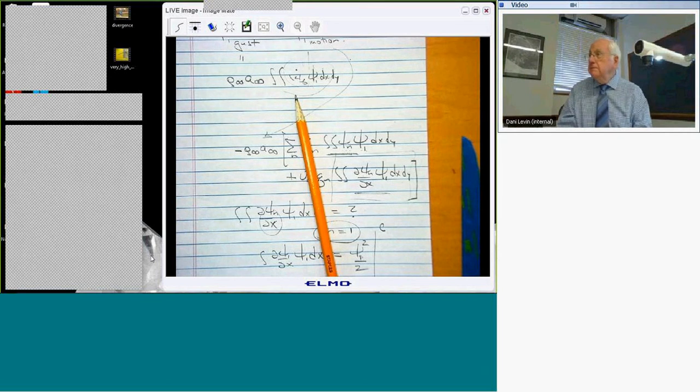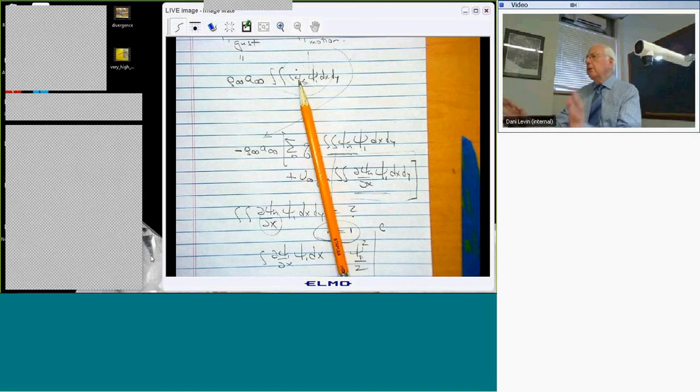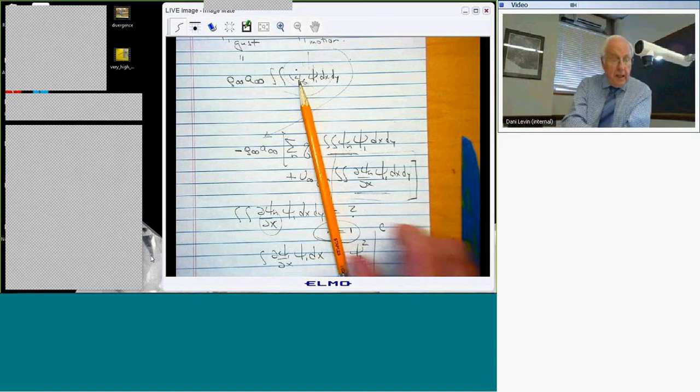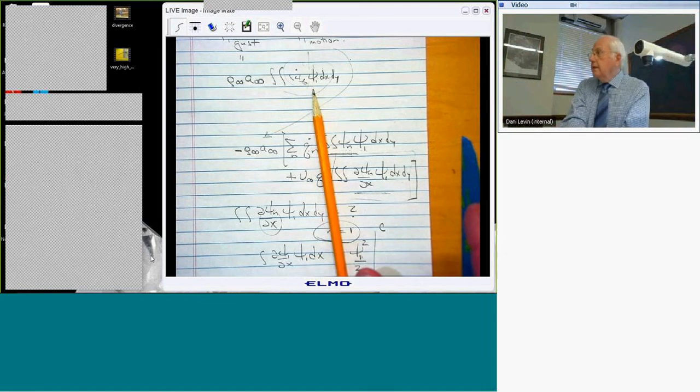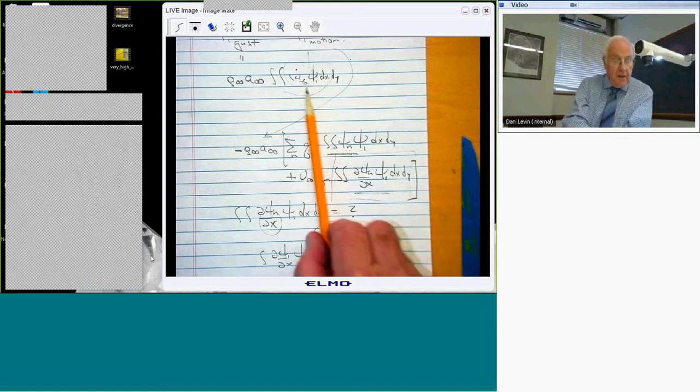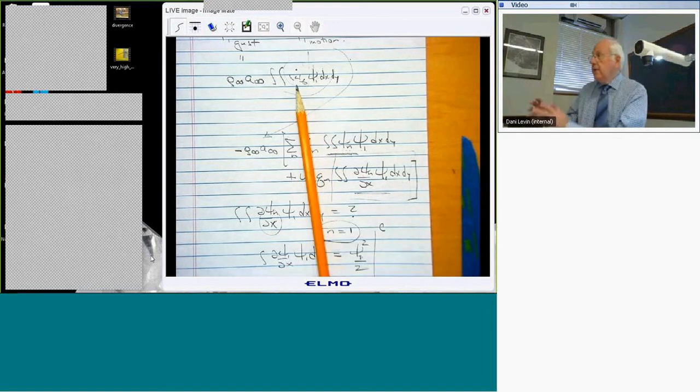No. Well, what do you mean by saying the gust velocity? The gust velocity doesn't know anything about the modes. The gust velocity is there because there's a random motion of the fluid in the atmosphere, and then an airplane comes by, which has some modes. But when I'm interested in which mode the gust excites in the structure, then if the spatial distribution of the gust velocity tends to match well with the structural mode, then that mode will get more excitation than some other mode. But the modes of the structure don't change the gust velocity.